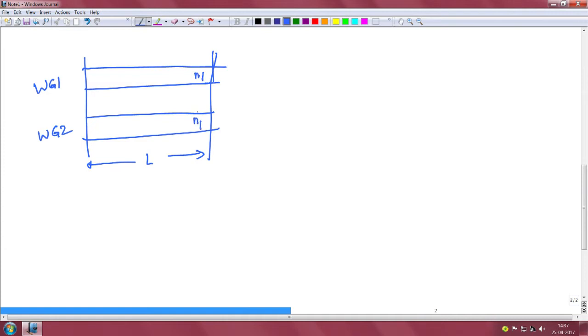Waveguides, they can be different, two different waveguides. So, the widths can actually be different and there is a spacing, we will say the spacing to be s. And of course, the waveguide width W1, waveguide width W2, we know the properties of the individual waveguide because these are symmetric slab waveguides, and we will assume that the propagation direction to be z and the waveguides are aligned along the x direction. This is the geometry that we can use.